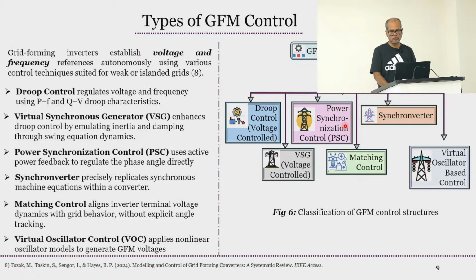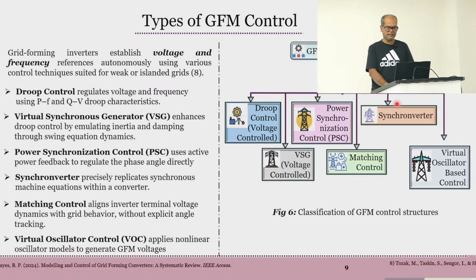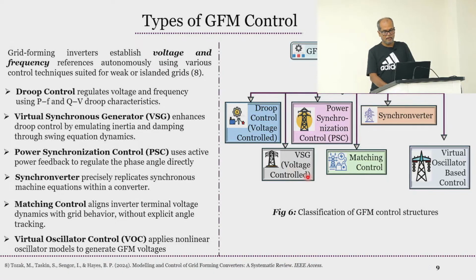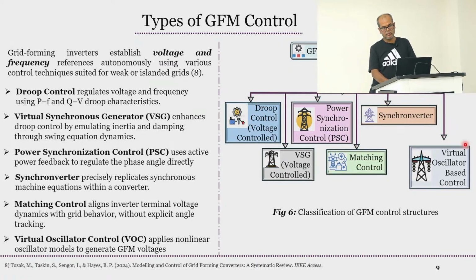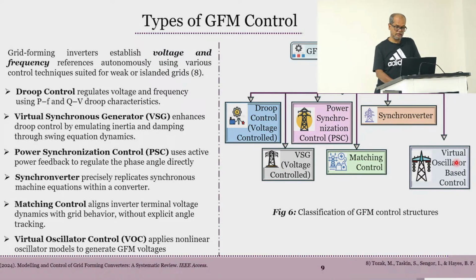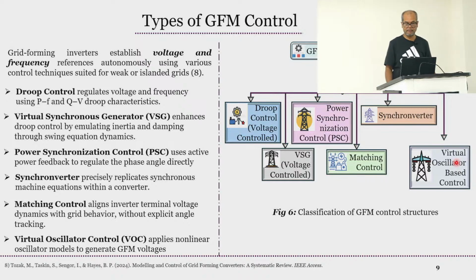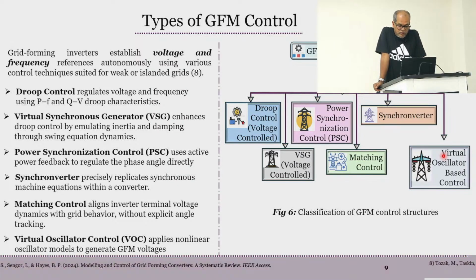We also use PSC, power synchronization control, and the synchro converter, which makes the converter behave like a synchronous generator, as well as VSM. People also use matching control and virtual oscillator based control techniques, which are also used for GFM. Some algorithms are similar with different inputs, and there are also newer techniques, but these are not all the techniques that Dr. Animesh discussed yesterday, which can be utilized here as well.